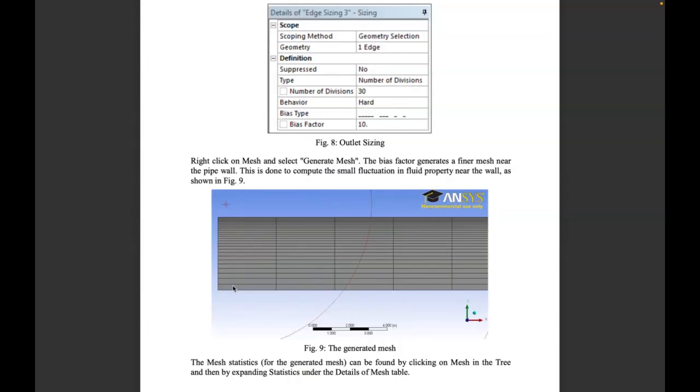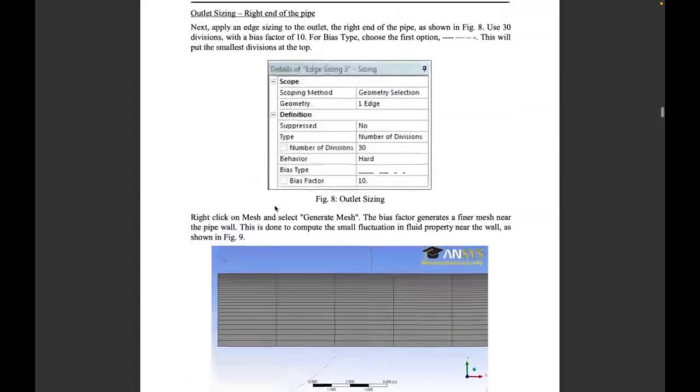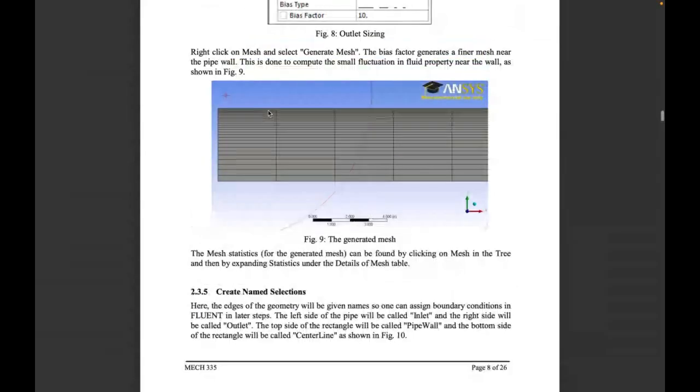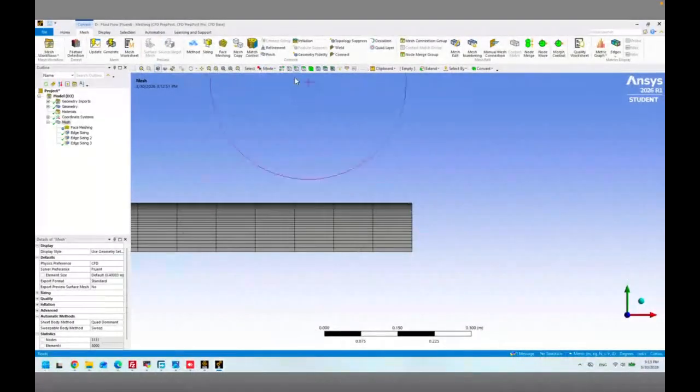and the bottom is coarse. What we just did is called an inflation layer. At the wall we care about the boundary layer representation. That's why we want a finer element size there, but we don't care about here. Here is the axial direction, so it doesn't matter much. Nothing big is going on here, but a lot of the physics we are concerned with is up there. So this is basically to accurately resolve the boundary layer separation due to the slip condition.